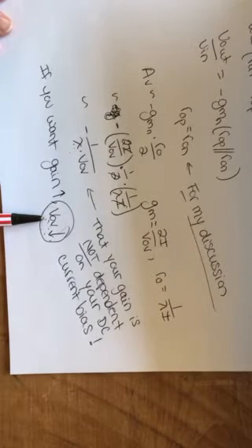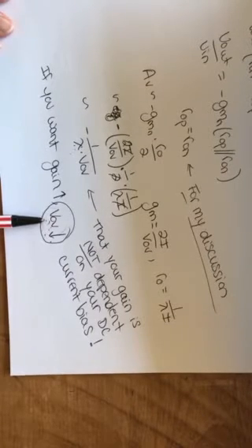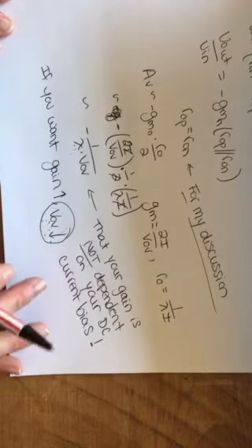So by giving you an overdrive voltage in this lab, we in essence have fixed a small signal gain for you. So if you don't have the correct DC bias on the transistors, you will not get adequate gain.